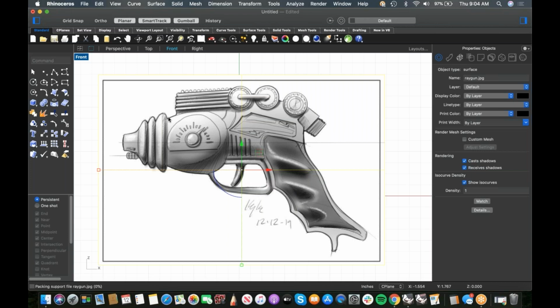The front of this basically is this kind of bulbous shape with these stacked things up into the barrel end here. We can look at that and say that's actually just a revolve shape. We just have to draw half of that and then spin it. Then this is a repeated detail that's just stacked on top of each other. We could probably even steal that detail from here once we've built it. This is a single repeating detail. This is pretty much just an extruded shape. That's a little revolved feature. We've got a little building to do here.